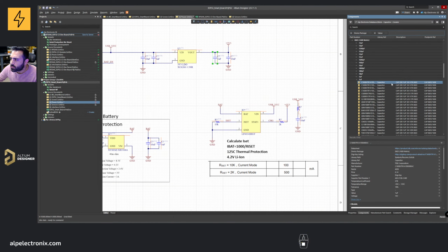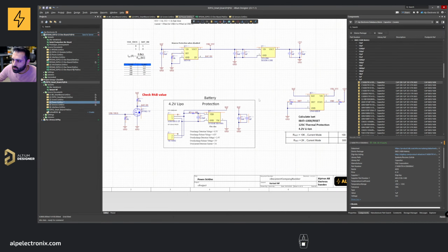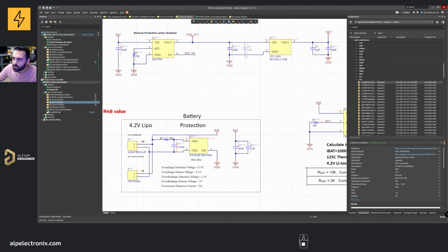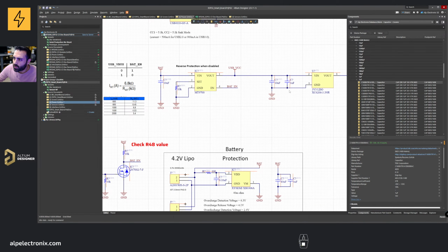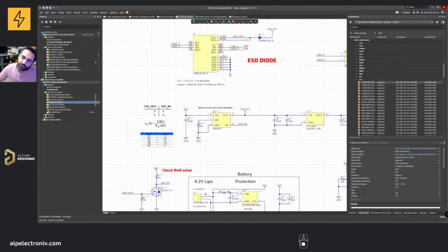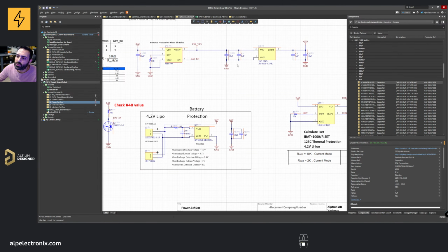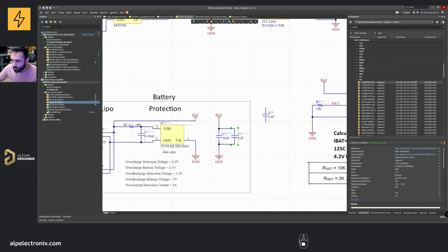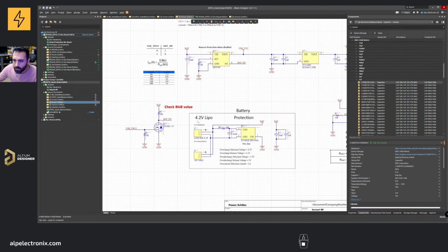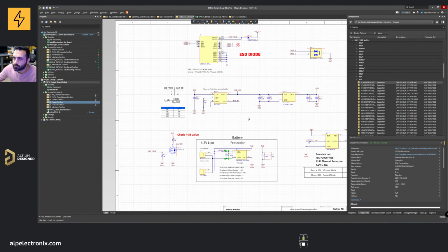Usually the voltage levels are important, but since this is 3.3, I don't care much. So that's why you should check whenever you do it. And the USB VCC in this case can be only up to 5 volt. Well, for the USB PD, it can go up to, I think, 28 volt or 48 volt in the new standard. I'm making a new USB PD as well. And then that's there. So these ones we need to check.